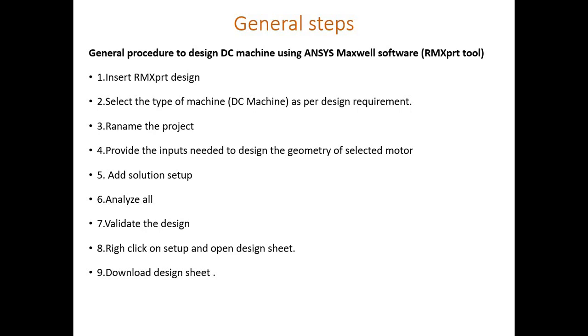Then you need to add the solution setup. Then we need to analyze the design, so that if there is any error, then that error will pop up and we need to rectify it. And then we need to validate the design. So what is the meaning of validating the design? That means if there is any parameter which is not within the acceptable limit or which is not as per the design standard, then it will show a red cross mark, and then we need to rectify that error.